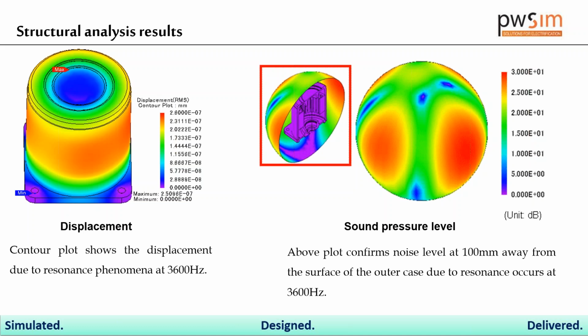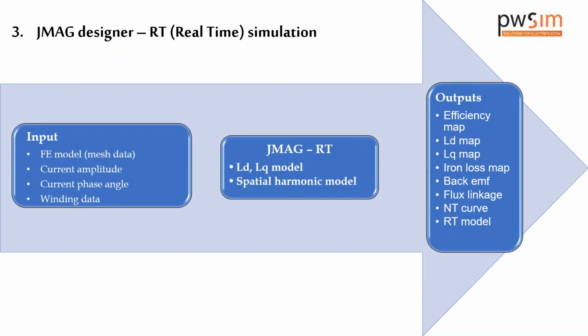Once your thermal analysis is ready, you can go for the structural analysis, wherein you will be developing electromagnetic forces and inputting the mechanical parameters, and based upon that you will be creating a study, and that study will focus upon the deformations, the noise levels, the vibrations that are happening within the motor. You must have heard of a number of papers, you must have seen NVH analysis, vibration analysis happening across the IEEE spectrum. So these are some of the ways you do all those things.